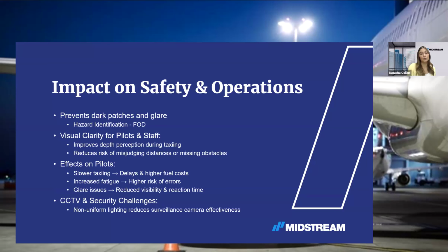Non-uniform lighting also reduces the effectiveness of CCTV and surveillance cameras. This is because cameras can't focus properly with inconsistent lighting. It only focuses either on the bright areas or the dark areas. So for CCTV, uniformity actually becomes more important than light levels.